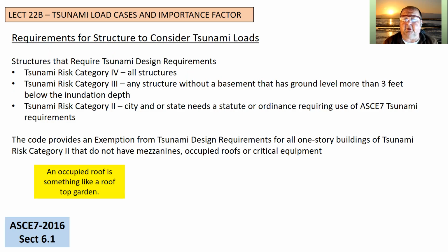So the building code goes through and then designates, you've looked at your building, you've looked at what is going on inside the building. If you're in that top risk category, no matter what, your structure has to be designed for these tsunami loads. If you're in risk category 3, which is not the most highest risk, but still they're critical facilities and they do pose a risk, then if my building has a ground floor that's going to have an inundation of more than 3 feet, I need to worry about tsunami loading.